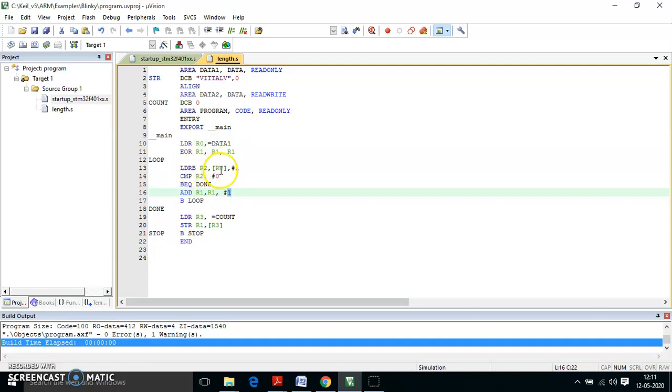So we are going to initially move only one byte, say for example V, and it will have an equivalent ASCII value as well. So one byte is being moved to R2. Now you know that the ASCII value of the corresponding character V is now present in R2. Now this R2 is going to be compared with 0, because once you execute the initial 3 instructions, all these characters will be converted to ASCII values. They will be kept in the default memory. So the ASCII values are already present in the memory. You are just going to fetch the values. So it will start fetching the value.